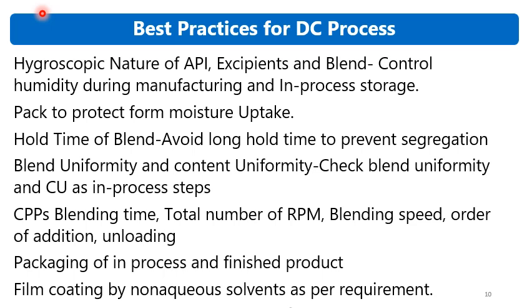So sandwich blending can be performed, in which the API can be co-shifted with excipient, and during order of addition, first add one third of the major diluent, then add the API, then add the remaining material followed by the remaining quantity of diluent, so that blending is proper.